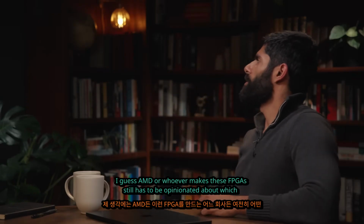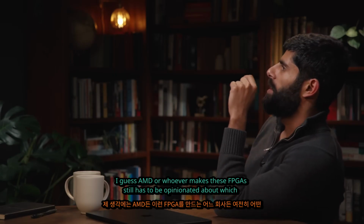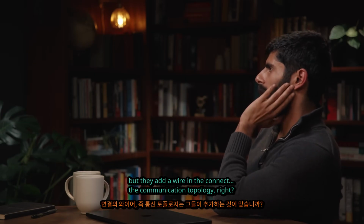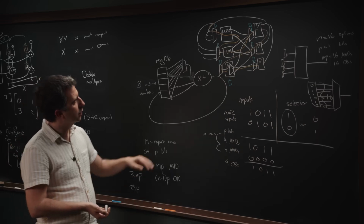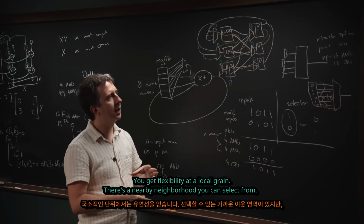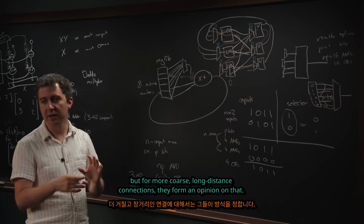Yes, yeah. And so I guess AMD or whoever makes these FPGAs still has to be opinionated about what registers should connect to which registers. And then you can program in the actual gates, but they had to wire in the communication topology, right? Yeah, so you get flexibility in a local grain thing. There's a nearby neighborhood where you can select from, but then more coarsely, longer distance connections, they form an opinion on that.